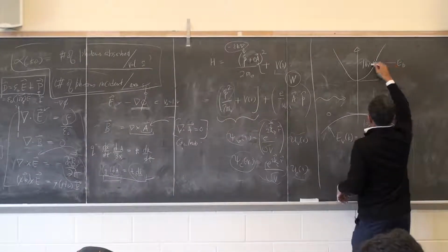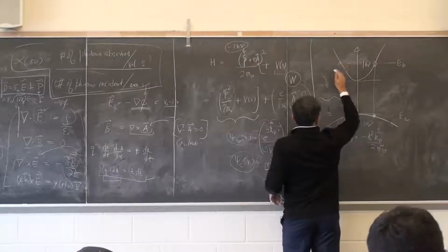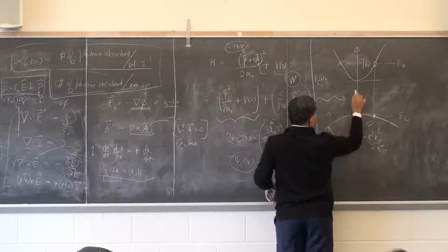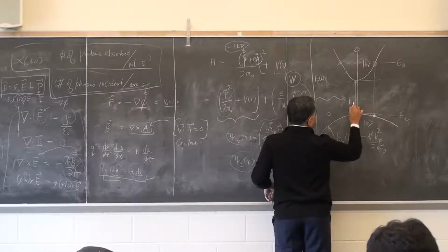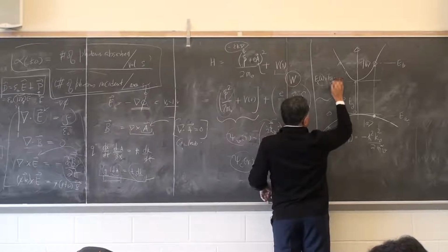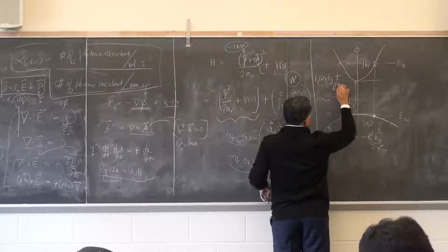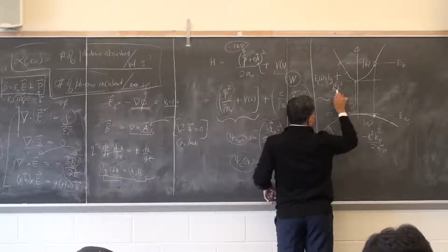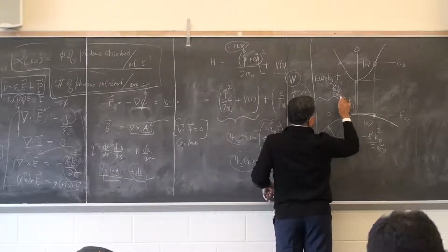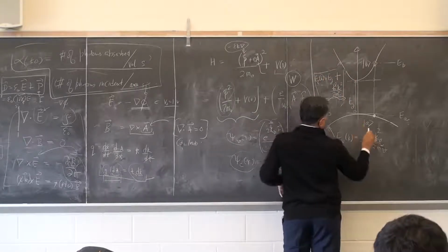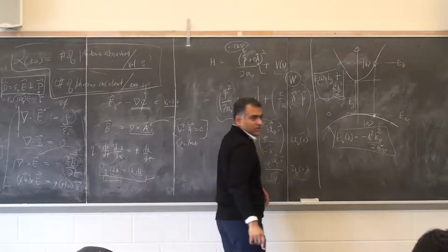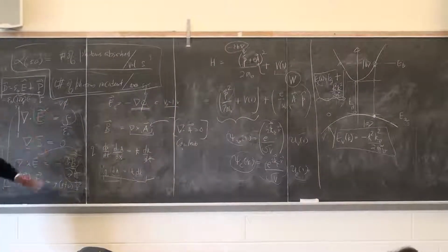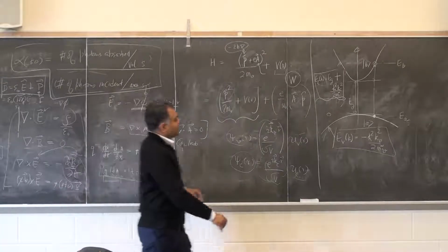Similarly, the conduction band states will be given by E_C of k equal to the band gap plus h-bar squared k conduction squared over twice the effective mass of the conduction band. Does that make sense? I've just written down the full band structure, and now most of the job is keeping track of every term.